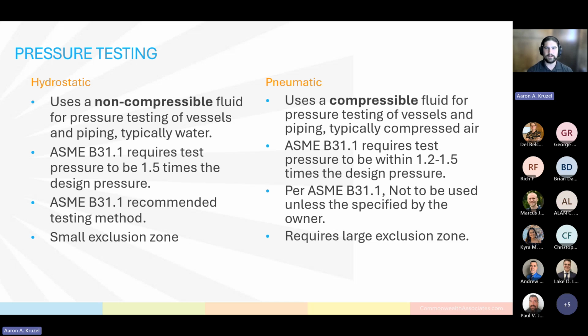So a major part of construction is testing in some way the pipe that we design. So making sure that the rigidity, the structure, everything is going to hold at a lower pressure by testing it at a higher pressure. So doing this, there's two methods, hydrostatic and pneumatic.